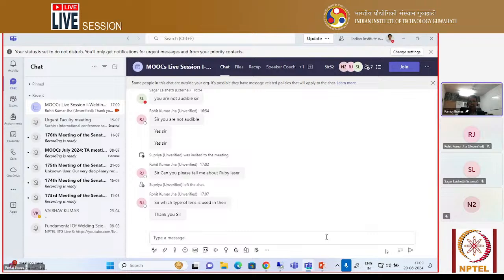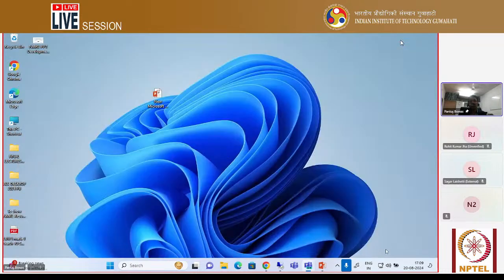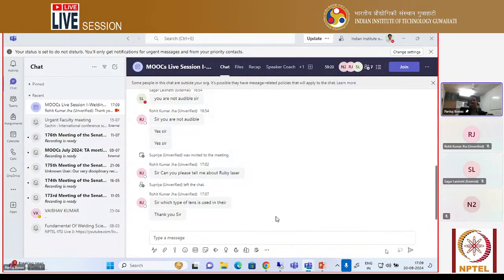So generally the XRD technique is mainly used for measuring the residual stress on the surface level within around 50 micron depth range. Whereas the neutron diffraction technique you can use for high depth, thickness residual stress measurement purpose. What I am telling, understand? These are the things you should keep in mind. So these are two very popular non-destructive residual stress measurement techniques.